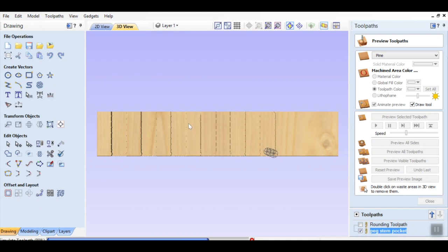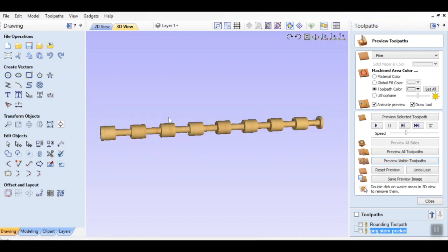And it looks like there's little jagged edges here. There's not really when it comes down because it's close enough that the bit gets that. And what happens when you do it that way is your bit's going back and forth this way and doing most of the machining instead of doing the machining as this rotates. And it's a little quicker. It works quicker, there's less vibration, and it gives you a job that's pretty clean.